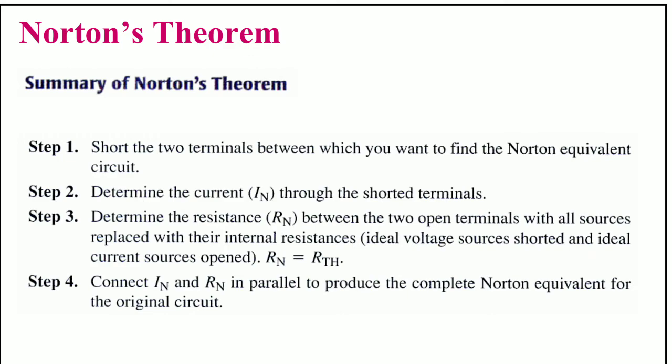Summary of Norton's theorem. In step 1, short the two terminals between which you want to find the Norton's equivalent circuit. Step 2, determine the current IN through the shorted terminals.